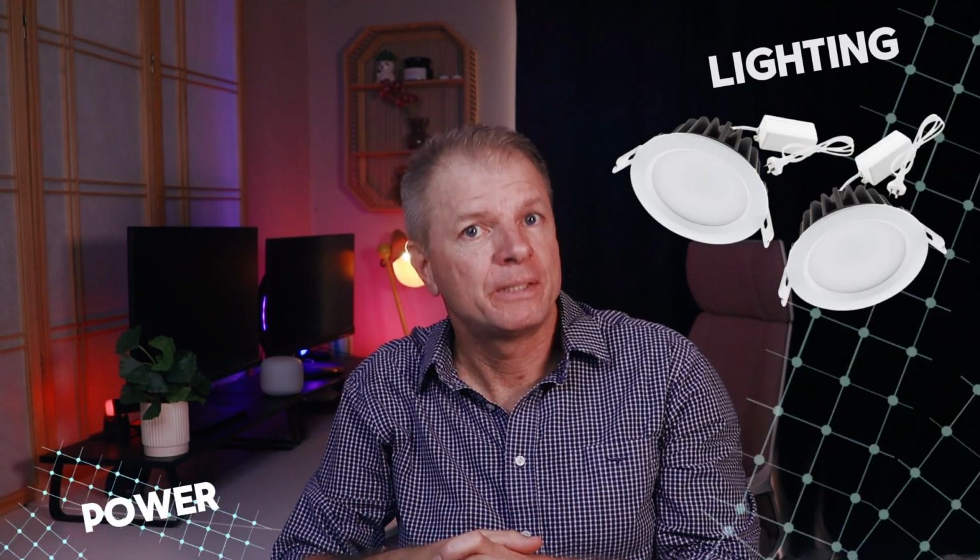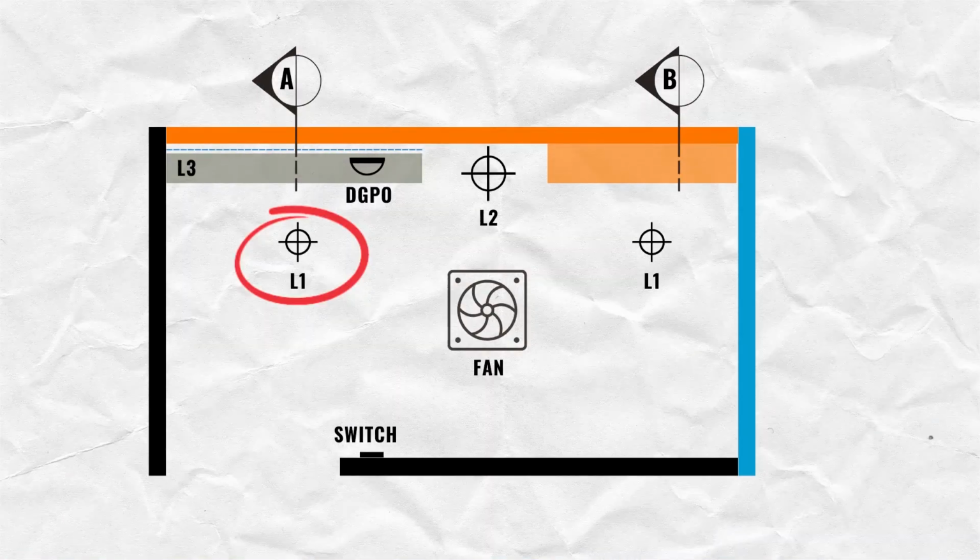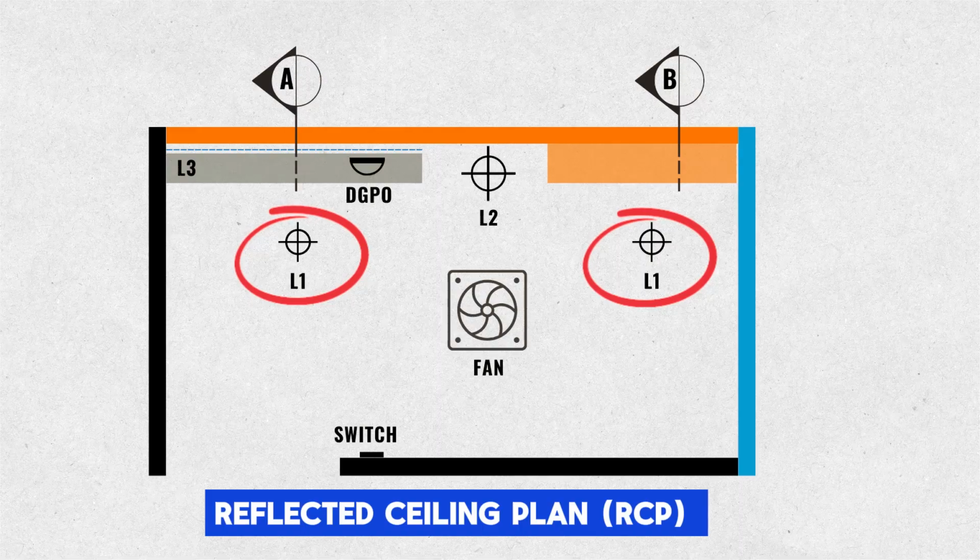Now on to lighting and power. I'll place two recessed downlights in the ceiling, one over the basin and one over the shower. This fitting outputs 1100 lumens, which is very bright and well suited to a bathroom. It is also IP65 rated, which means it's suitable for wet areas. If you don't have much space in your ceiling cavity, there are recessed downlights that are more slender than this one, or you may need to select surface mounted fittings or use wall mounted fittings.